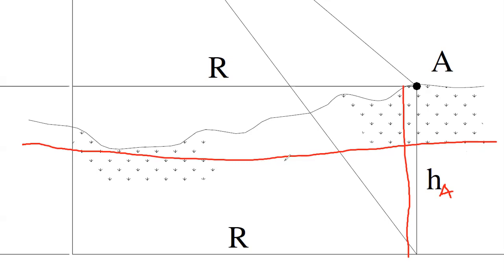All right, then there's not much relief. Also, let's not forget that a building can also be considered to be relief, because it also has a height. This can be a 50 story building. Are you okay? Going through that is also relief. So on the photograph, these things tend to shift.